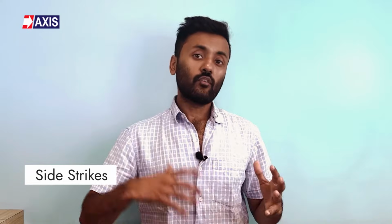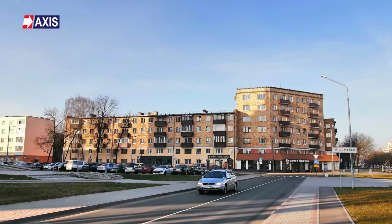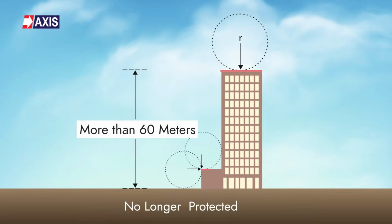Irrespective of the radius of the rolling sphere that you end up using, whether it is 20 meters or 60 meters, side strikes could occur on buildings that are higher than the radius of the rolling sphere. The probability of these side strikes is negligible on structures less than 60 meters in height. Therefore, as you can see in this drawing, even though the rolling sphere is touching the side of the building, because the height of the building is less than 60 meters, its sides will be a protected zone against side flashes. But if the height exceeds 60 meters, then the side is no longer protected and is therefore susceptible to side strikes as per IEC 62305.